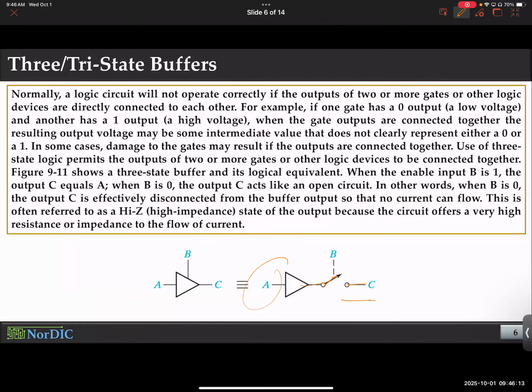So that introduces a new state which we haven't seen before. When something is not connected to anything, the output is literally, as I'm going to use the term here, floating. You don't say that the output is zero. No, zero is something that you impose. You drive something to zero or drive something to VDD. You don't disconnect and just assume that it's going to be zero or VDD, because you don't have any control over the output now. You don't know what the output is going to be because you don't connect anything.